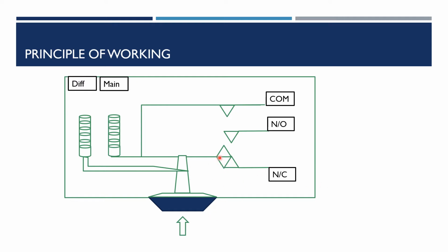So if you connect it here, the circuit starts as closed, and you can see that the contact of the switch is already connected with the normally closed. That's why if you connect your circuit, you're gonna see that the circuit is on, or the circuit is complete and closed. So this is related to the terminals, and we're gonna talk about it in detail in the next slide. But let's agree on this as the terminals for the connection. Common is always there, normally open for an open circuit, normally closed for a circuit to be considered closed from the beginning.